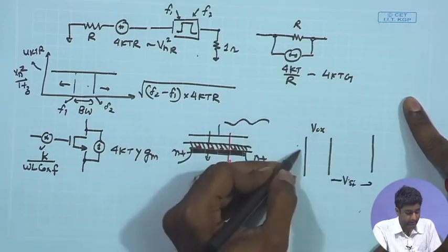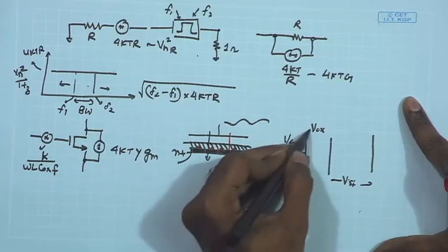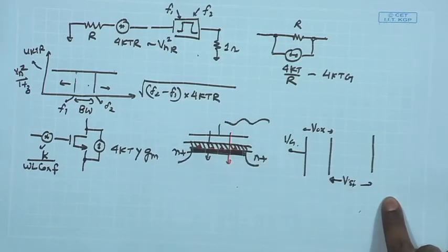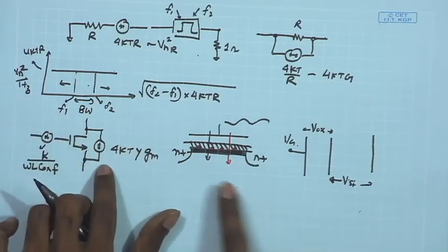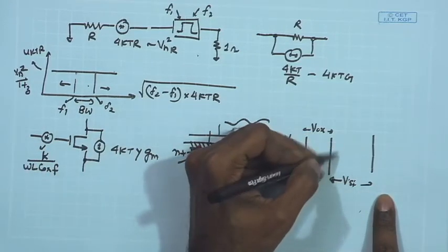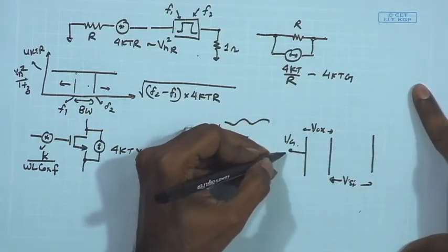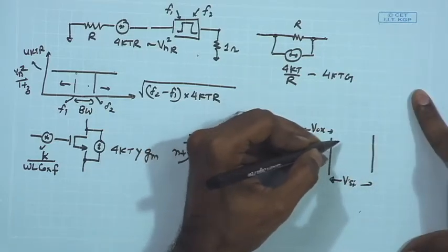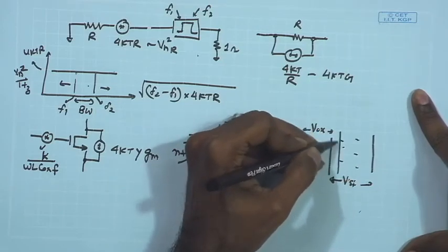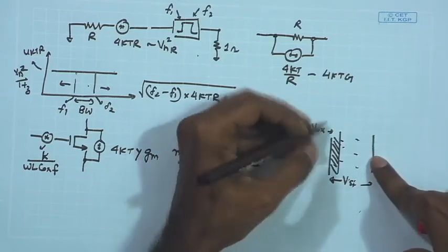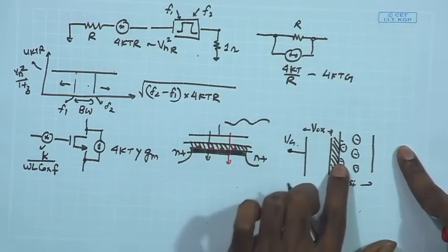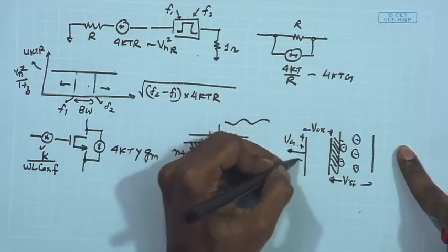So, when we apply a gate potential VG, we have an overall voltage drop across the oxide and some voltage drop across the silicon, and here the voltage drop across the oxide depends upon the total charge produced in the silicon. So, for example, when you have a certain gate voltage, you have a depletion region created in the p type silicon, and you have some inversion charge created close to the channel, and as a result, this total depletion charge in the p type silicon and the inversion layer charge combined together are supposed to balance the total positive charge that you put on the gate.